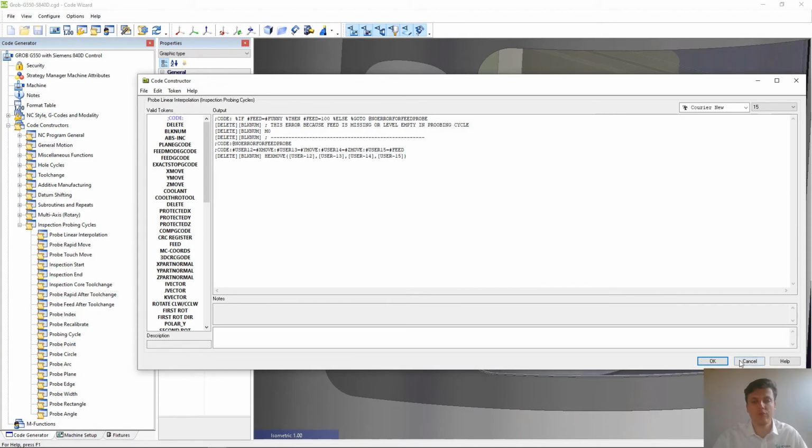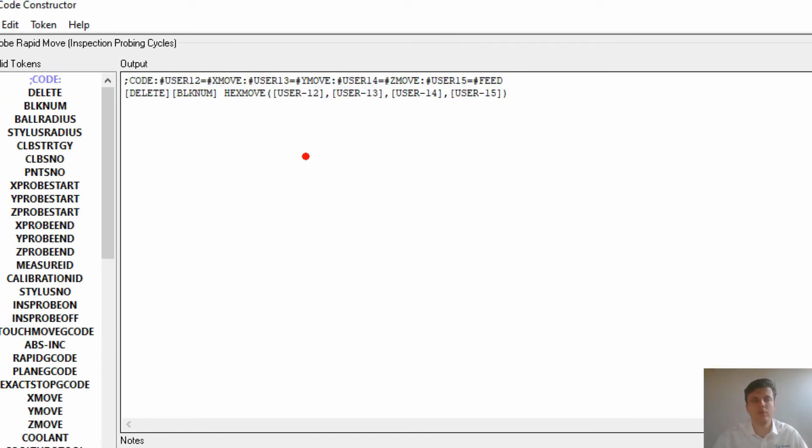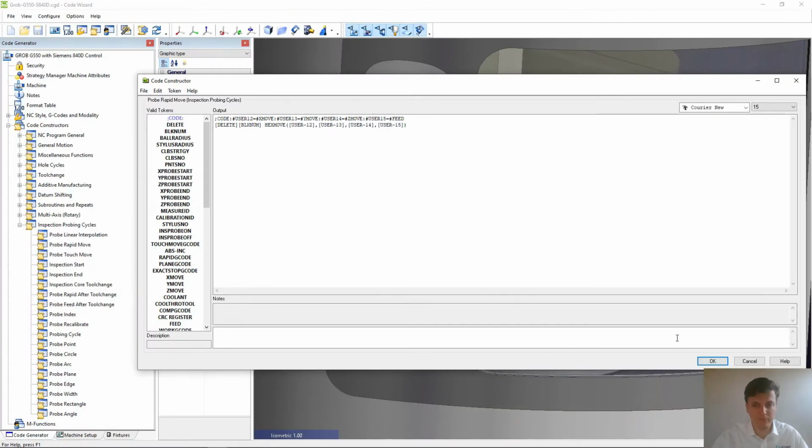As I mentioned, you have two options for positioning. You can use the installed macros. For example, in the previous Doosan one, I used the Renishaw position macro, a protected movement, but on this one I'm using the hex movement, my basic macros. So I have to copy, in this case, 3 macros. One is the hex move, basically containing the X, Y, Z and the feed movement.